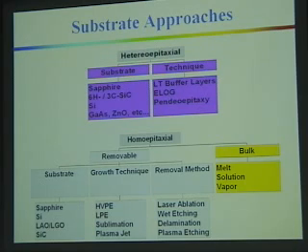We've improved on the dislocation density by several tricks. One, probably most popular, is to do lateral overgrowth. That is to open windows into a mask and have deposition occur selectively in the window openings and not on the mask material. As the gallium nitride grows selectively in those window areas, it will eventually exceed the height of the mask and then grow laterally and eventually join each other. And that area over the mask material is relatively dislocation-free. That has problems too with limited use of area. There's problems where the material meets, but it is the material choice for the laser diode fabrication that occurs today.